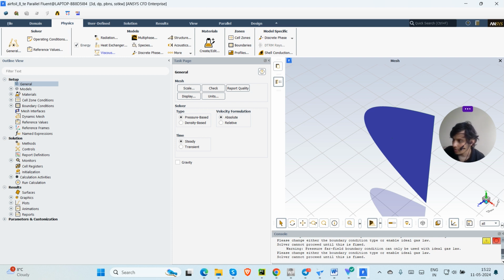Physics, cell zones, and boundary conditions. Materials defined are complete, so proceed to zones. The default material of air will be used, so no need to set any cell zone conditions. Click boundaries and open the boundary conditions panel for far field boundary. At pressure far field boundaries, required inputs are the Mach number, static pressure, flow direction, turbulence BCs, and static temperature.